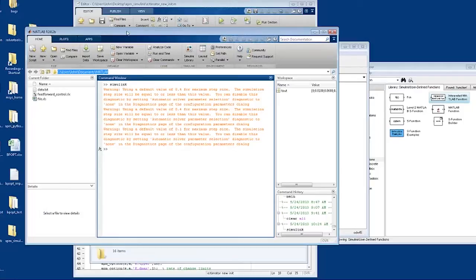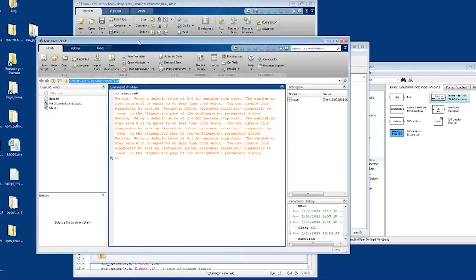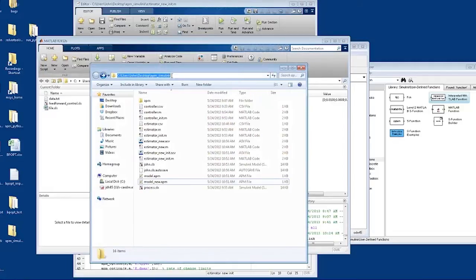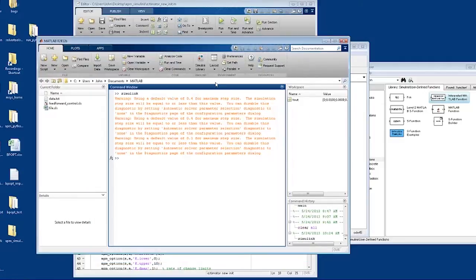If you go back to your Matlab screen, just change your directory to that Matlab folder that we're using, because it couldn't find the function. Go ahead and select it, copy your path, and then all of your things will show up in the left-hand corner under your current folder. Okay, so everybody have that?